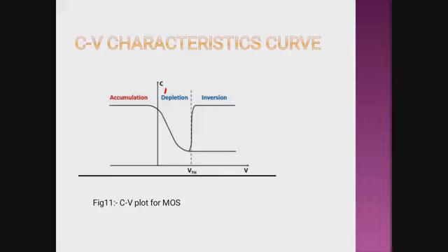But in the high frequency case, due to the increase of the depletion region, which I have already discussed in previous slides, which varies with the applied input voltage, and the substrate which acts as a parallel plate, the overall capacitive effect is falling or gradually decreasing, because due to the increase of the depletion layer inside the MOS, the total distance is gradually increased.